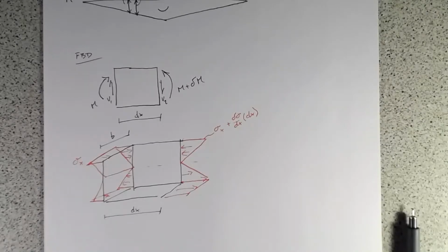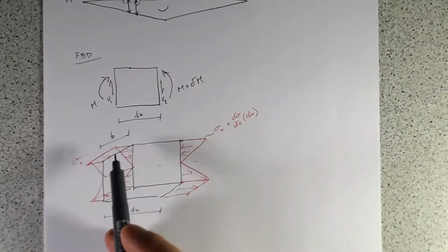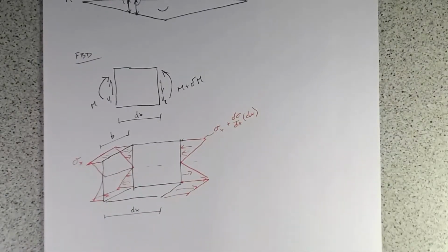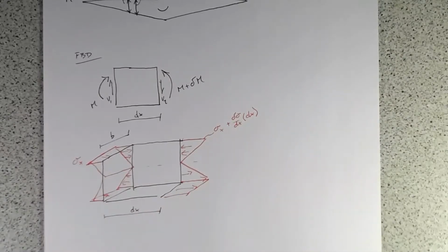If we want to find what our shear stress at a point is, we can take into account that if we cut off the top here, we're going to reveal the longitudinal shear stresses. Because where we have two surfaces meeting, our longitudinal and our transverse shear stress need to be the same. That's essentially the tactic we're going to use to determine what this transverse shear stress distribution is.